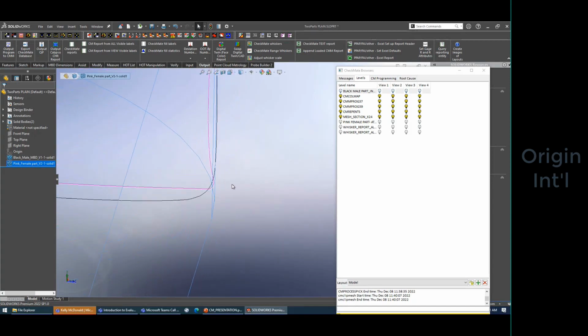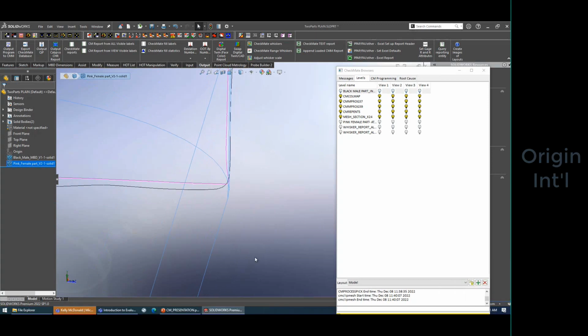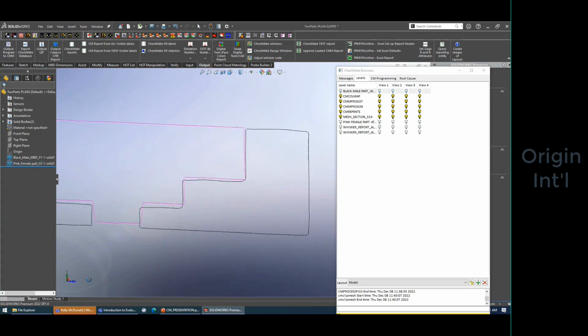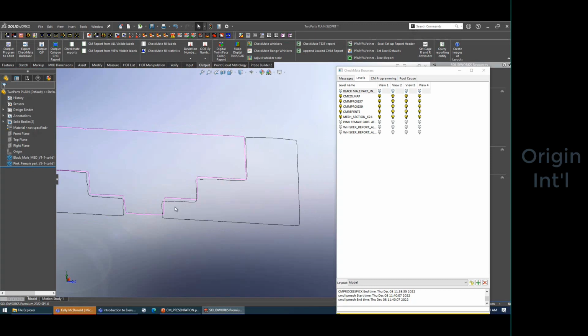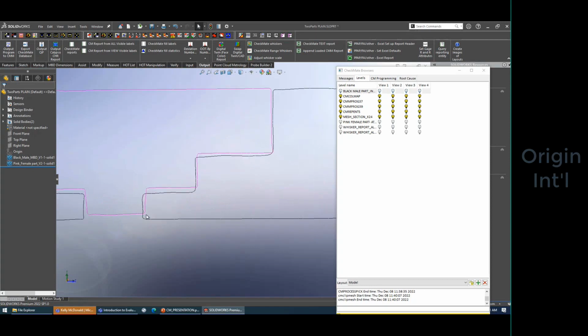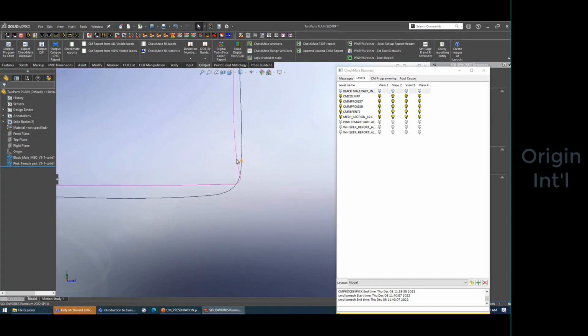And you can see, taking this massive point cloud with all this great data in it and dumbing it down to what's going on with my part, you can really see. Wow, that's amazing. You can see that you've got some problems here, and you've got another major problem here of why it's not going down any further. There are some functional issues here of why these parts aren't going to go together. And then you can just continue with that. So, you use the color maps at your component level to tell you if they're good or bad.